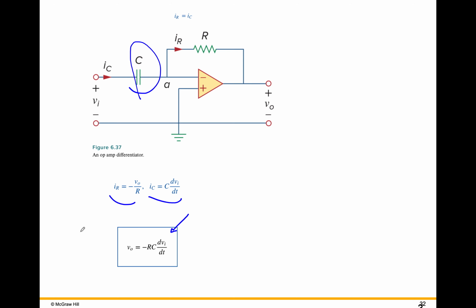First of all, inductors tend to be large physically, so it's difficult to manufacture them in a chip, and even sometimes hard to breadboard. And inductors tend to be more difficult to procure commercially, so sometimes you would have to wind your own. Given that it'll accomplish the same thing and is significantly smaller and easier to find, capacitors are used in differentiator and integrator circuits.